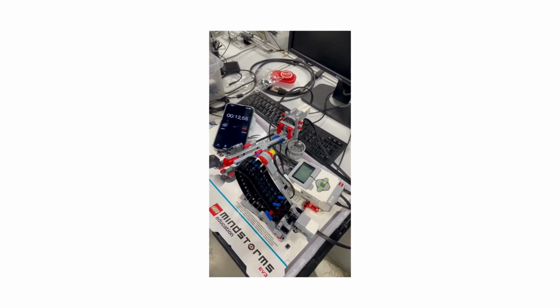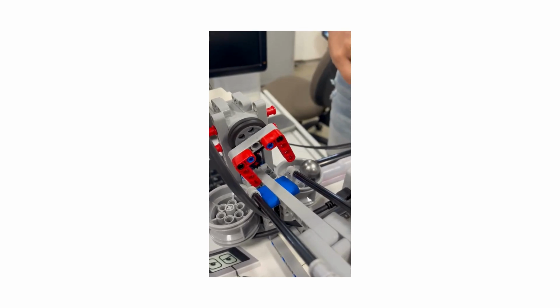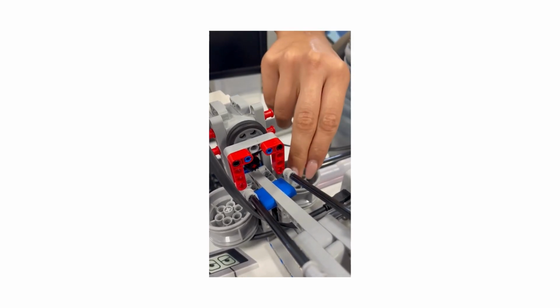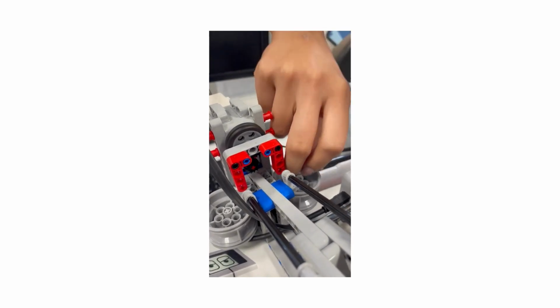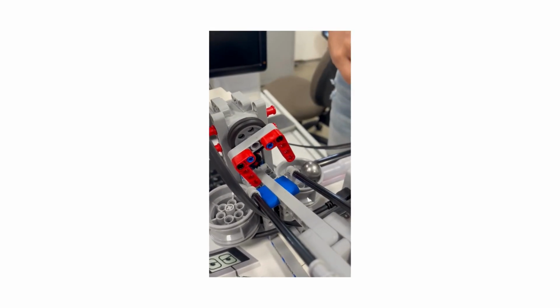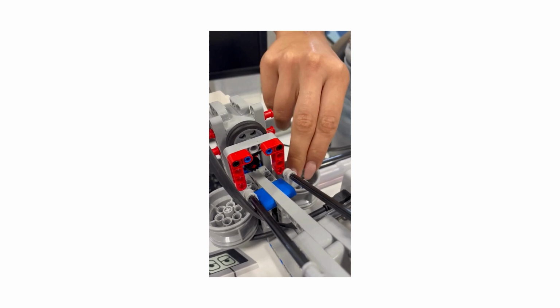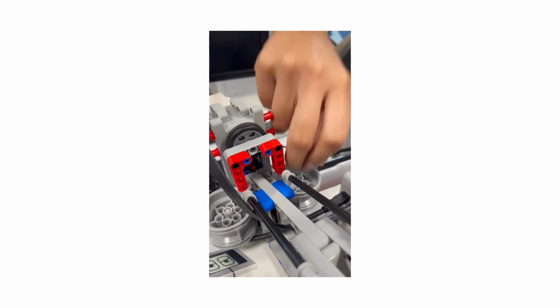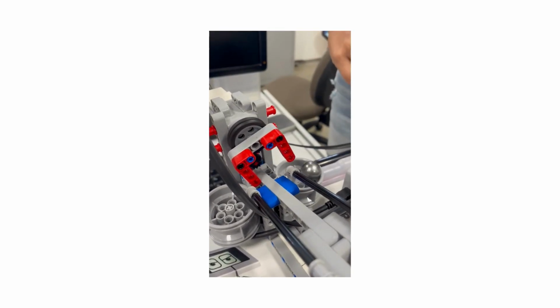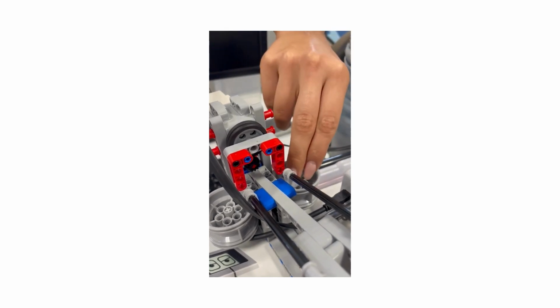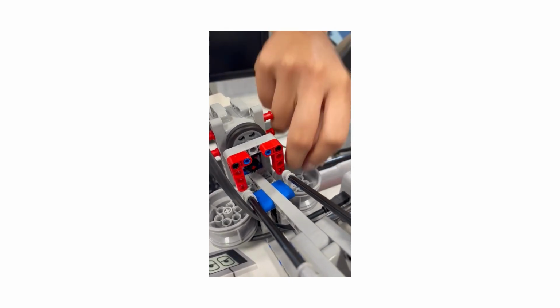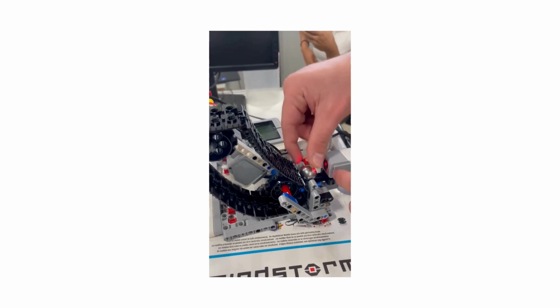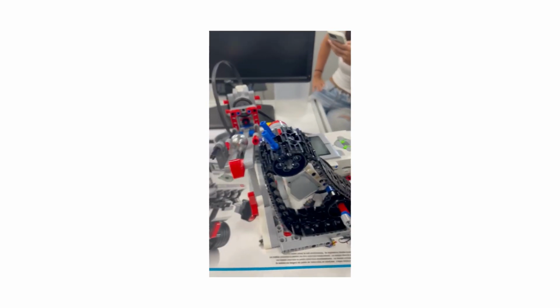Second change, in the conveyor motor initialization, the original code used -300. So in the Python code that is belt_motor.run_until_stalled(-300, stop=Stop.BRAKE, duty_limit=30).